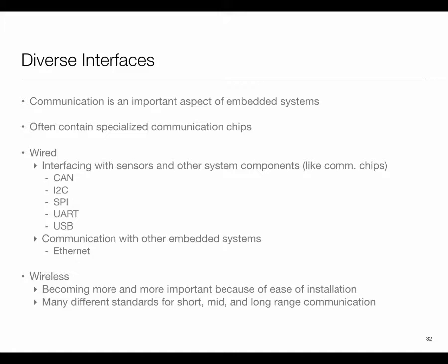So whenever a packet goes out, before the packet are some bits which help the receiver learn the rate at which the sender is sending and where the bit boundaries are. In the synchronous mode, things are kept synchronous, and therefore data can be pumped much more rapidly. You'll typically see that in asynchronous mode, UARTs may go up to maybe 100, 200 kilobit per second, but in the synchronous mode, you can pump up to maybe a few megabit per second. That's the performance benefit you get. And then USB, USB 2.0, 3.0, all those things.